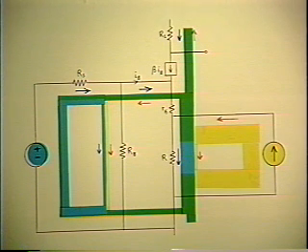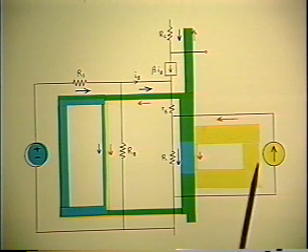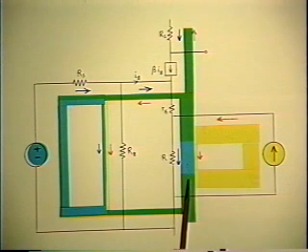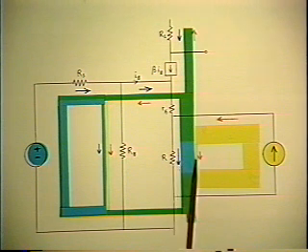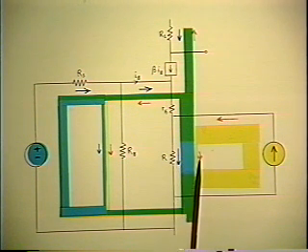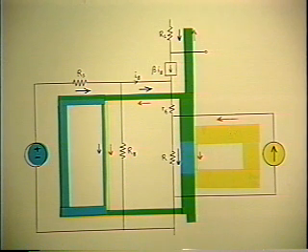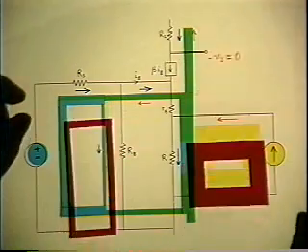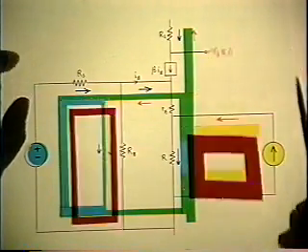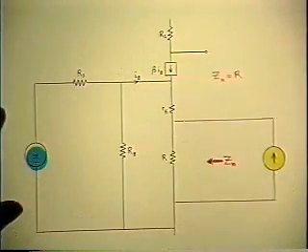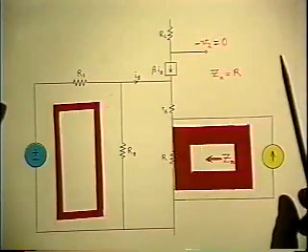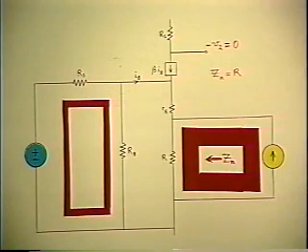Namely, both the base and the emitter. Therefore, all of the current from the yellow source must be going down the resistance R. Here the blue and the yellow are in the same direction, so they add, they don't cancel. And the total is the same as the yellow current that was going in, because the green is 0. Okay, now the only non-zero currents are those. Now if I take the first two away and leave only the net result, subtracting out the null part, that's all that's left.